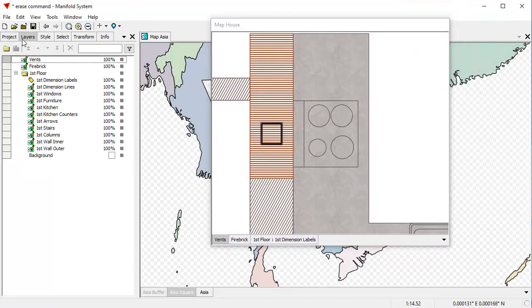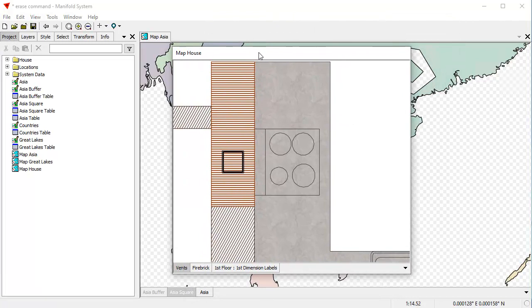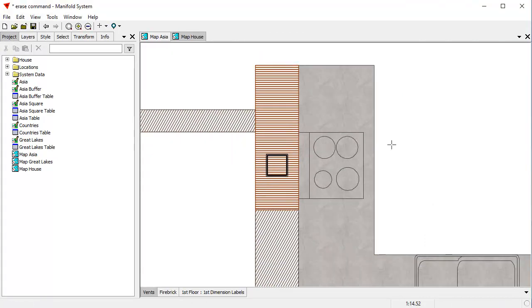This one, for example, has a lot of layers here. They're all grouped inside this layer group, and those all work together at once. Let's dock this. I'm going to right-click and dock that. Whereas in ArcGIS Pro or QGIS, you're only limited to one structure that has a bunch of layers in it. With Manifold, you can have unlimited numbers, and layers can participate in different structures.